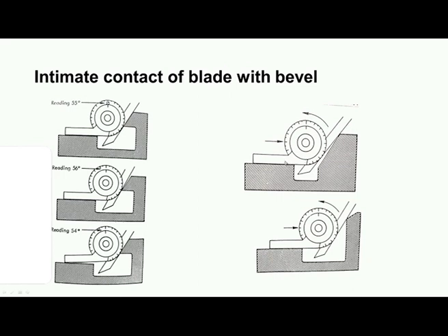So, again see, when one blade should come in contact with one surface of the workpiece, and then we should slide the protractor like this till the other blade comes in contact with the beveled surface, and then further we should push the instrument so that there is a proper contact at this place. Then we should take the reading.